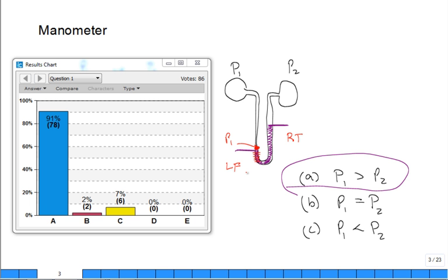Isn't it increasing? Yeah. If I think about going up, up, up until I get to this point right here, which is at the same elevation as the left-hand side interface, let's just say this is, I don't know, call it point B. What's the pressure at point B compared to the pressure at 1? They're equal. There's a little logic in that. Hopefully you followed it, okay?